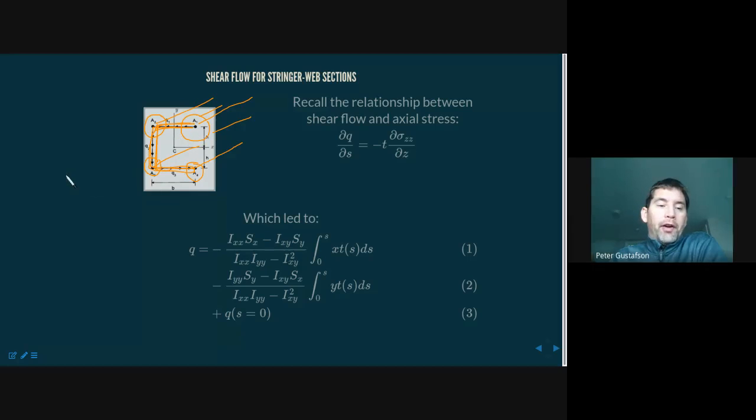Rather, it may be something that is more like an I-beam, or maybe even like a C-channel or something like that, where now it's a really thickened portion of the spar, something like you're seeing here rather than this. But this is an idealized, easy to calculate first entry into this concept,